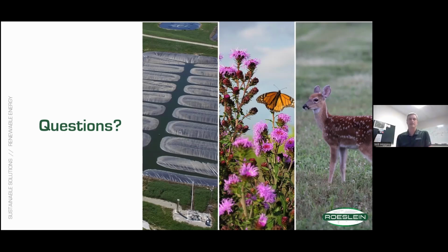Not so much in technology, but just in how much power they use. We find that the PSA is a little bit more sensitive to starting and stopping. It takes longer to get it up and on spec than a membrane system does. It's more hands-on for the operator when they are changing the flow rate or changing how they want to operate, it's a more manual adjustment, whereas with the membranes, you set them and pretty much forget them. So it's a much easier day-to-day operation.